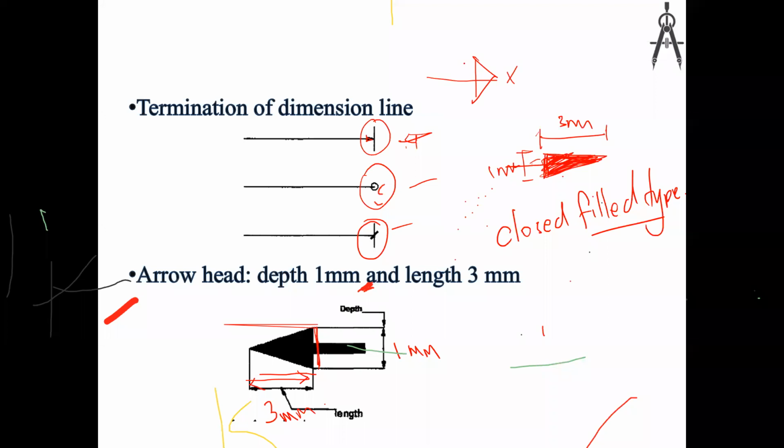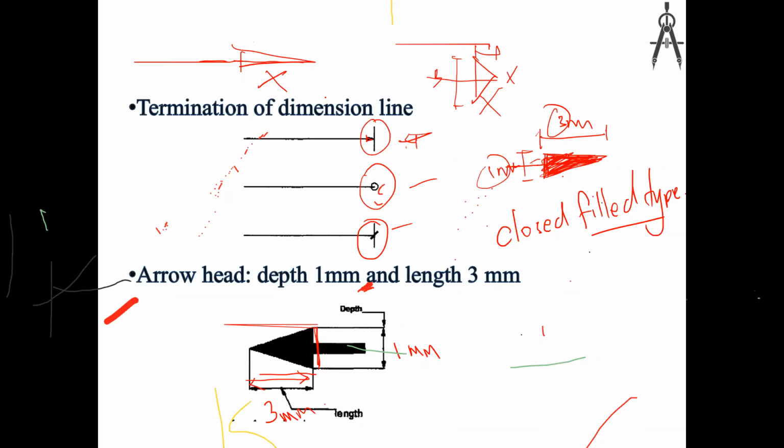You should fill it, and this is not the proper length. This is 1 millimeter and this one is 3 millimeter. If you draw it incorrectly or don't fill it, that is also wrong. If you draw like this, it is also wrong. So you should be careful about this.